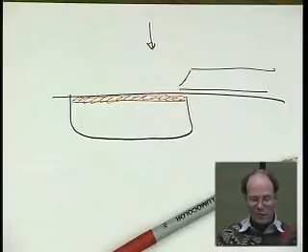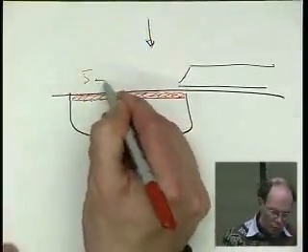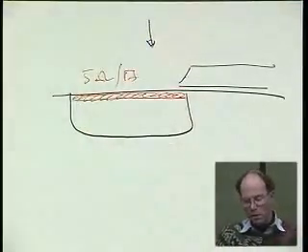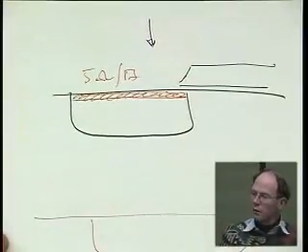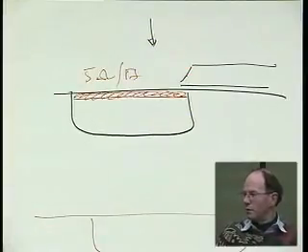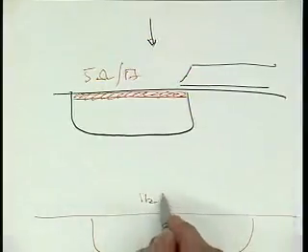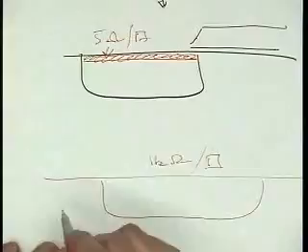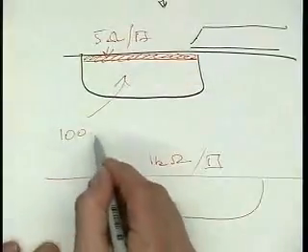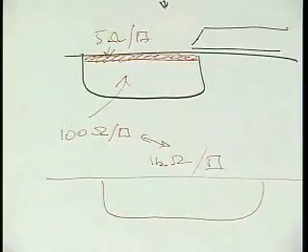Okay, so it's really the silicide that is the reason why we get such low 5 ohm per square sheet resistance. There would be hundreds of ohms if we didn't have that. That explains also why the well has so much higher sheet resistance. Well, in the well we don't have silicide. Simple as that, right? So here we get 1 k ohm per square. And here we have the 5 in the silicide option, and here we have maybe 100. This difference, of course, is simply because of different doping concentration.